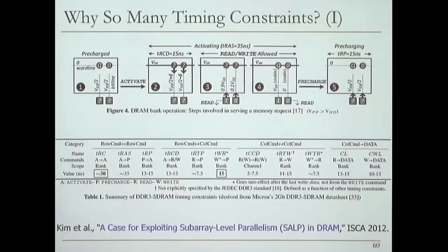So after you activate it, the sense amplifier is still operating over here, basically. Remember, the next step of the sense amplification is restoration of the charge. The sense amplifier figured out that this is a 1 and this is a 0, but now needs to restore the data back into the word line that you're reading, or the bits that it's connected to. So that takes some time.